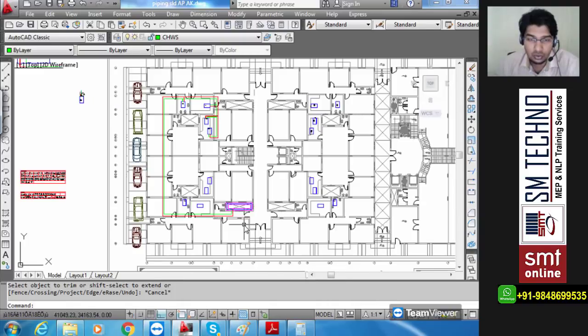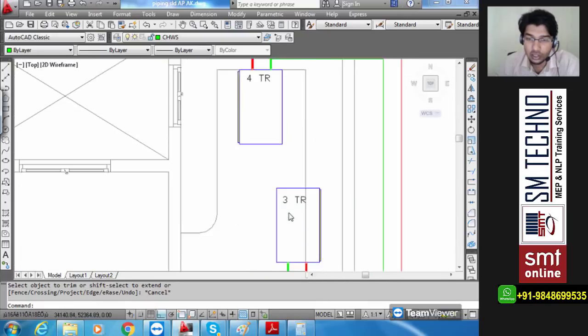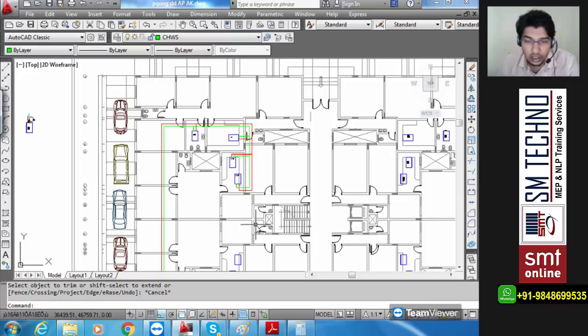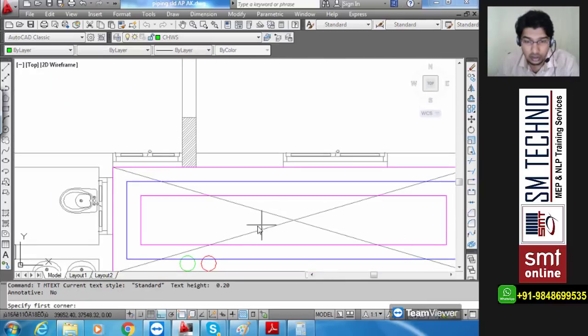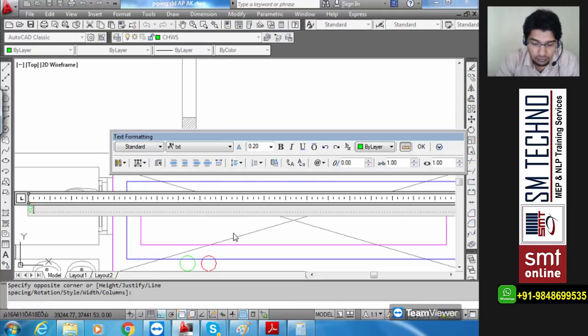Here also you can see, if you are zooming out, how neatly my pipe has gone and connected. Is it correct? Now what we have to do is the inside homework. That is nothing but for each and every AHU we have to provide how much is the GPM. Depending upon the GPM, how much will be the pipe size. Clear? So very quickly, I'm going to start that from the chiller. I'm going to consider a chiller of 850 TR.